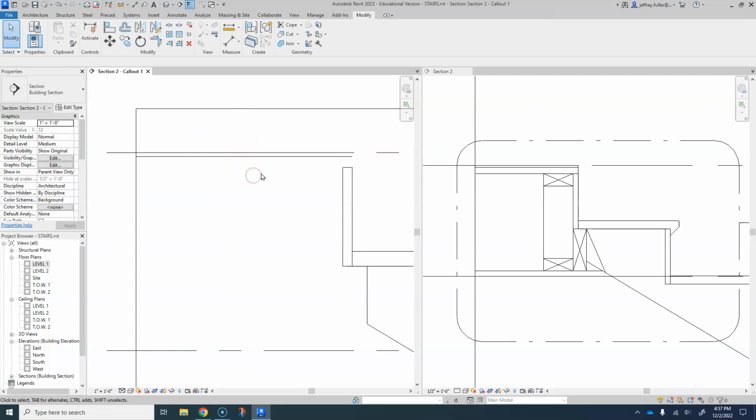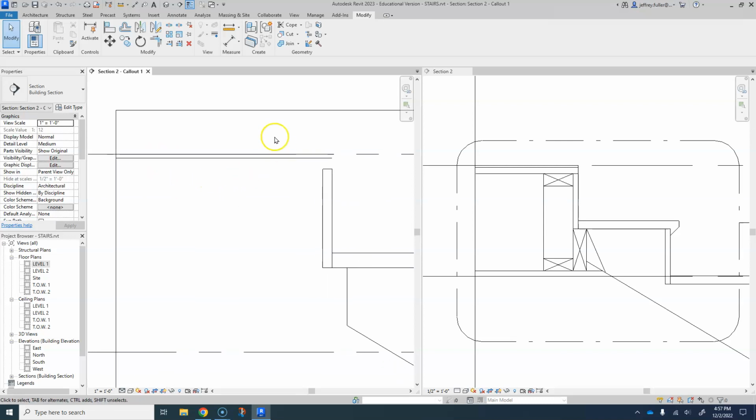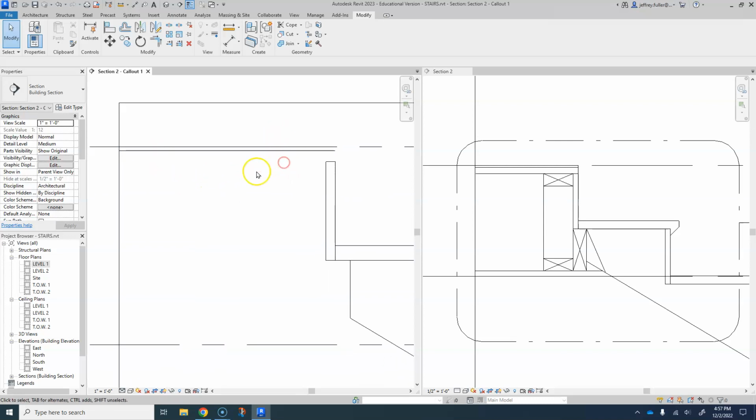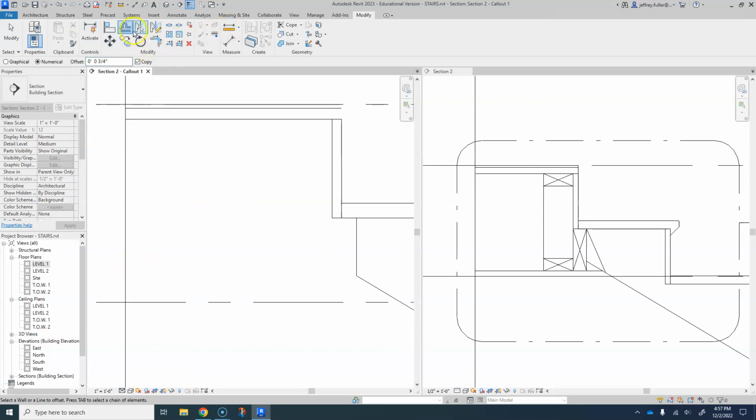Set it down there. Okay, so this level line, level 2 line, has to come to the very top of that floor level in drawing. Okay, it's the only room to draw. All right, next one is going to be offset 3/4, and that's going to be that plywood goes right there. Okay, now I'm going to draw me some 5/8 drywall.